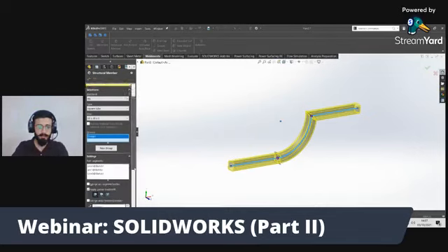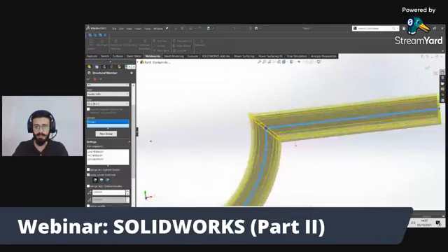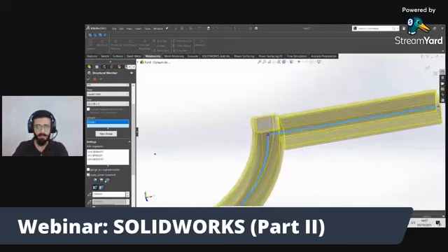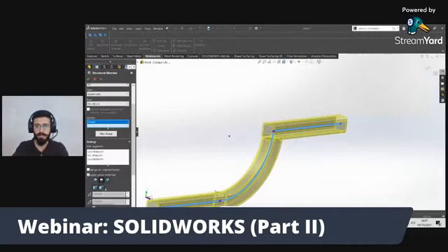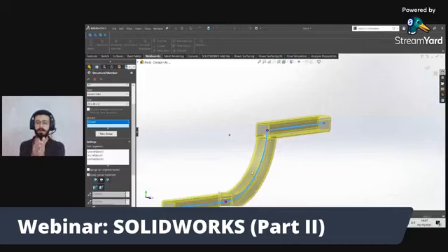But we can change its shape also. Like we can select the joints. See the type of this joint, and we can change this joint like this. We can change the joint like this. We can change the joint like this. This is how it's welded. If you want to make this joint separately in fabrication, this is the benefit of weldments. You can show your worker, you can show your fabricator how you have to make this. If you just want to bend the whole pipe through the bending process, you have to select this option.